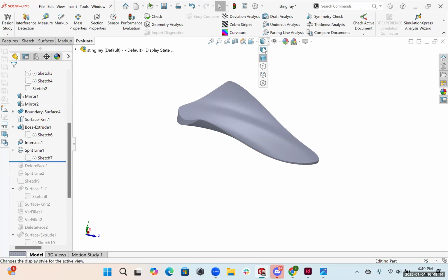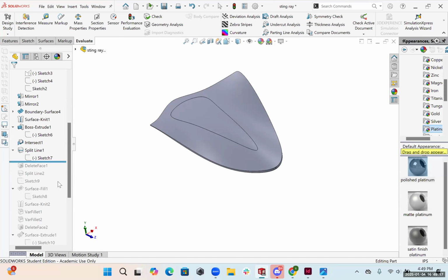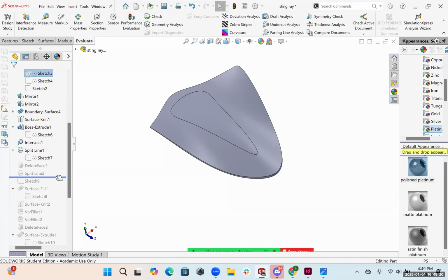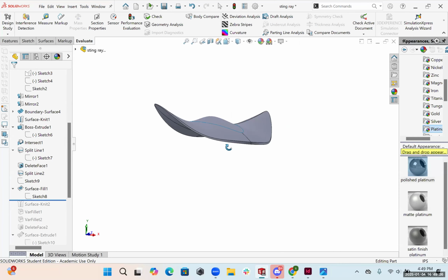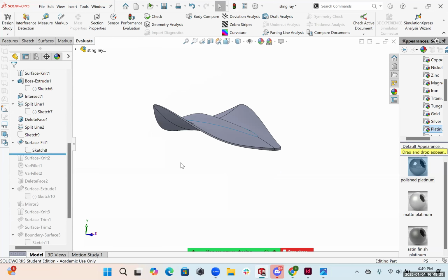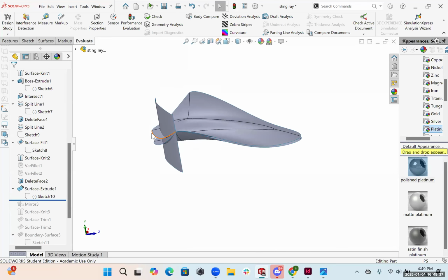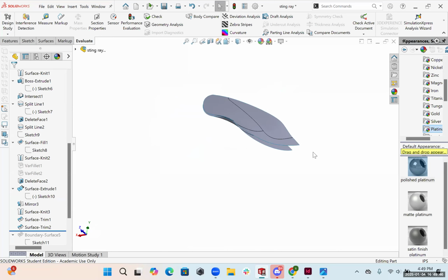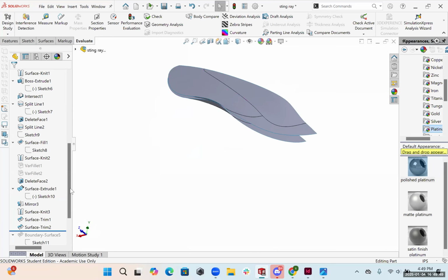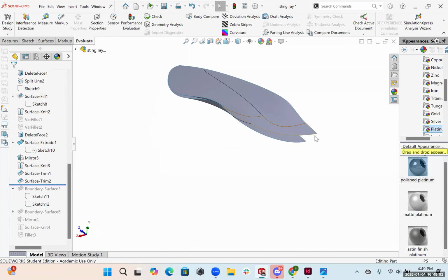So we are here. We are creating a surface split on the top, removing that portion, and recreating another surface. You see that? And here, if you look, this edge is pretty sharp, so we come in and remove that. And to create a nicer blend, I'm adding a surface to trim the bottom. Here I went to half again because it would be too much work to just do the 2 sides, and it may not come together as cleanly, so it's better to work on half of it.